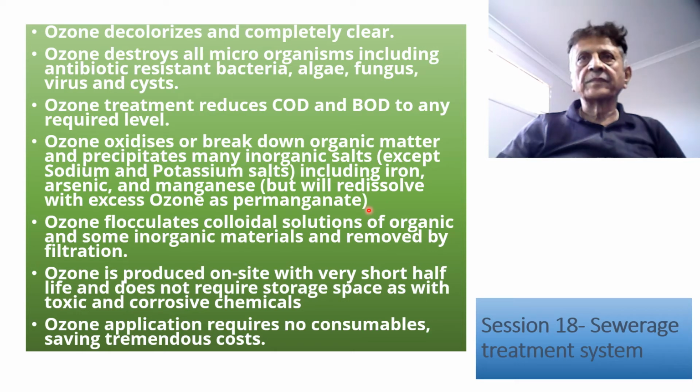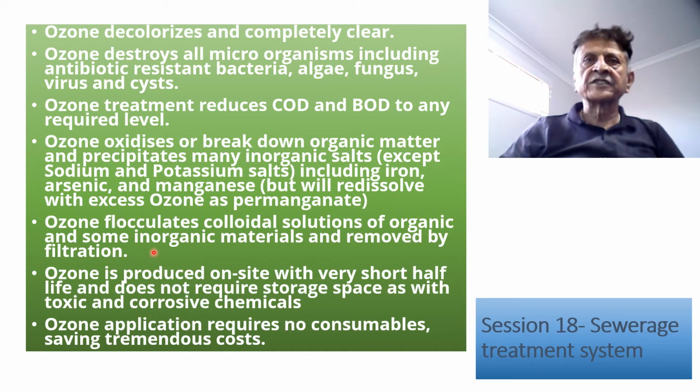including iron, arsenic, and manganese. But please note the manganese can redissolve if the ozone is in excess, and it will become permanganate. Therefore, we have to make sure that we don't overdose, if it is known that there is a very high quantity of manganese salts in there. Ozone flocculates colloidal solutions, both organic and inorganic, and they can be removed by filtration.